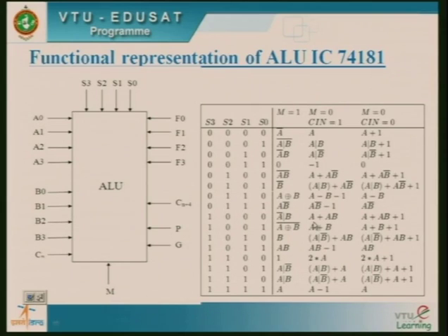Suppose I consider A and B as the variables. I can perform XNOR operation, OR operation, and then multiplication operation here. So these are the mode controls. With this mode control we can perform all logical, arithmetic, bitwise operations using the 74181.